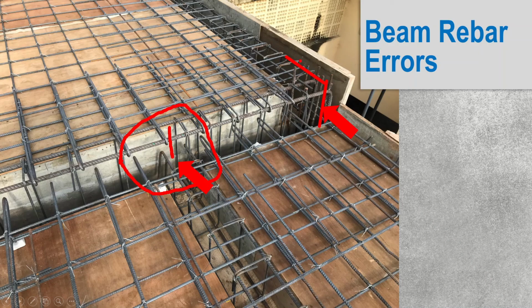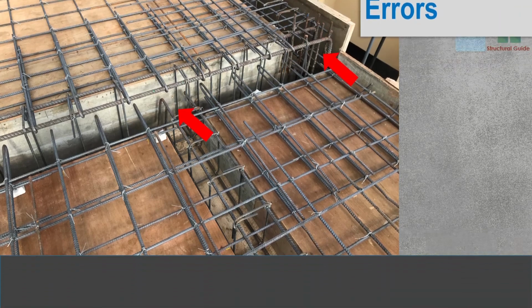In addition, you can see here the column reinforcement has not been treated properly. If you are not continuing the column reinforcement, it should be properly anchored into the beams. That also has not been done there. Therefore, there are a lot of issues in this reinforcement arrangement. These need to be corrected and should be avoided. So what you can do is get a proper advisor or proper supervision before doing the construction. We shall avoid these kinds of errors during construction.